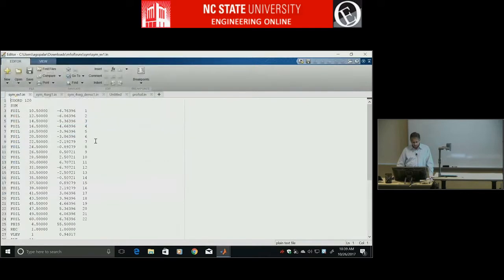Yeah, I think this is the airfoil I give you. So this has got 22 segments. You could just use this itself. And when you have a large number of segments like this, you normally don't go and change alpha star for each one by hand. You use the alpha star distribution window that we'll talk about soon. So you can graphically edit some alpha stars.